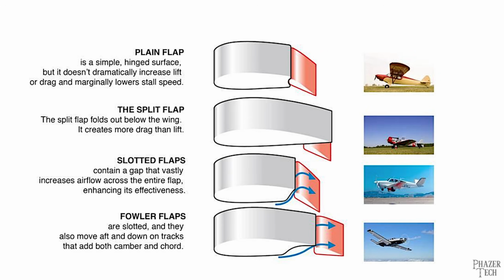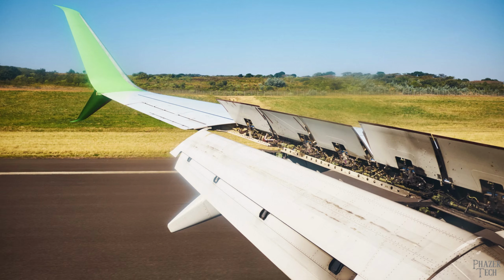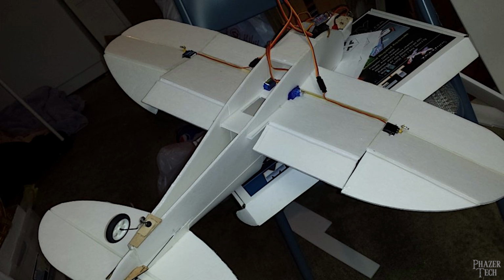One example could be small airplanes and their flaps. Flaps are used to change the shape of the wing, which alters the plane's lift and drag. The range of rotation for a flap will depend on the specific plane, but generally speaking their range is pretty limited, and are certainly less than 180 degrees. Now, while commercial airplanes typically use hydraulics to control the flaps, smaller airplanes and especially RC planes will typically use servos to control the flaps.